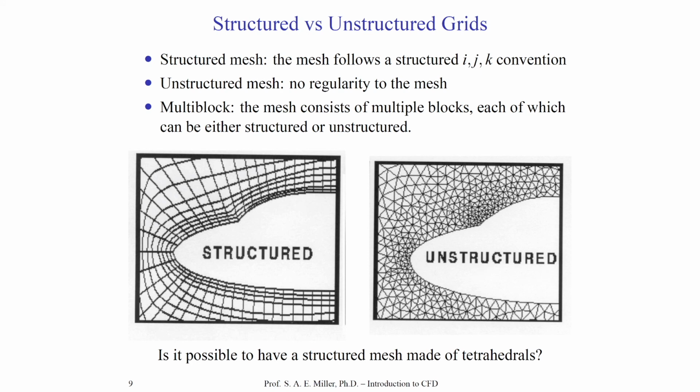We have previously talked more about these unstructured domains. Here again, you have a list of nodes, but we do not necessarily have to put the nodes in any order in any list or numbers in any particular order. We no longer have to say that in the lower right, this might be node 1, 2, 3, 4, 5, etc. But we can actually say that this is node 1, this is node 2, node 3, node 4. The order in the nodes no longer matters because we explicitly give a list in a file for the solver to read of the connectivity.